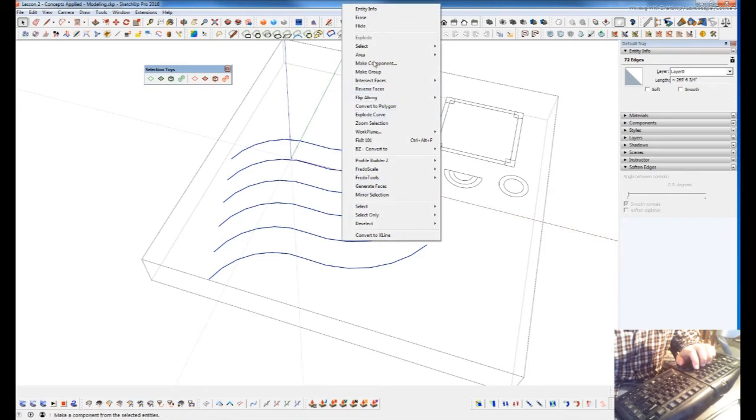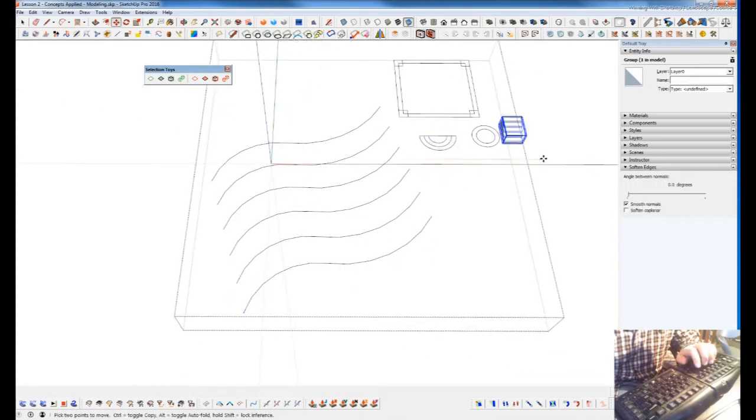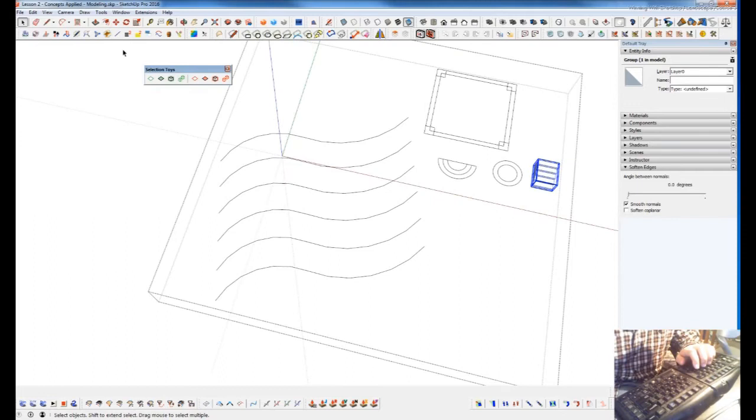And you can use that simplify curves option. So even if you imported these from AutoCAD and now they're just all edges here, and these are your contour lines, and it's important that they're all welded together, I can use my path select, double click, and select one and weld it. Or what I would do would probably be to move this over, select all of them, deselect these. Now all of these, I just have edges.